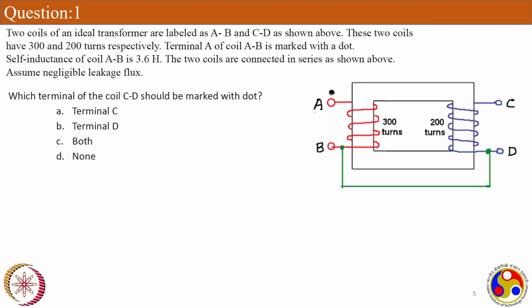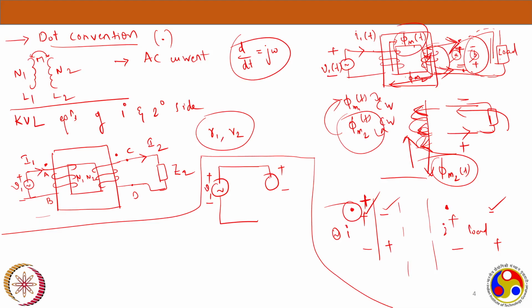That is the notation you use, because the voltage is minus d by dt of N phi, so you can replace that d by dt with j omega. Now I'm writing the self-inductance term, j omega, that is d by dt, L1 I1.